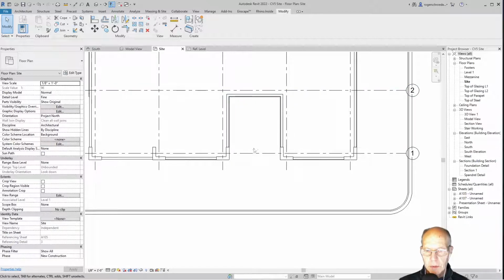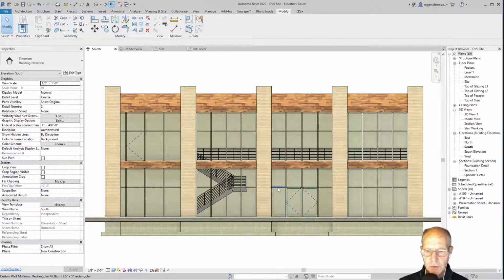And the depth is, this is a 20-foot bay, so if we were to have it touching the wall and wanted to stick out a little bit, we might want it to be 20 to 22 feet. So I'm going to use 16 by 22 as our guide for the size of this. If we were to look at this from a front elevation, this is 8 feet here. We might want this thing to be up about 12 feet, so I'm going to use that also as a vertical guide.